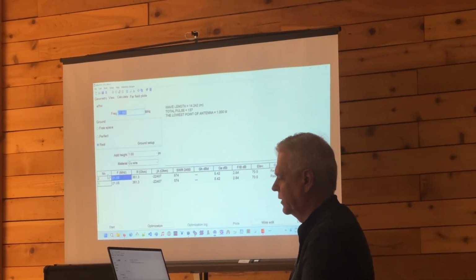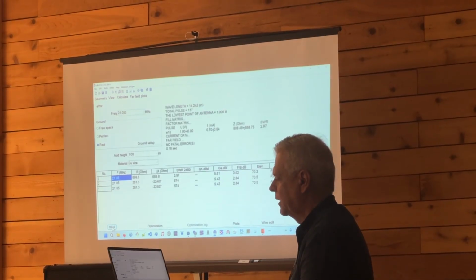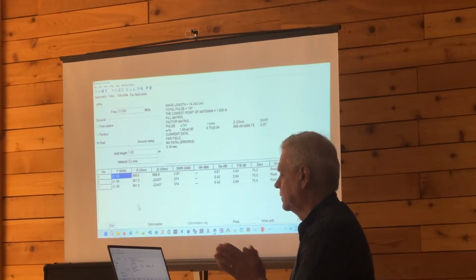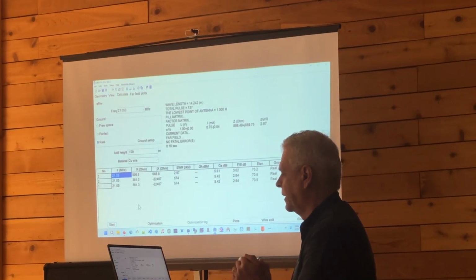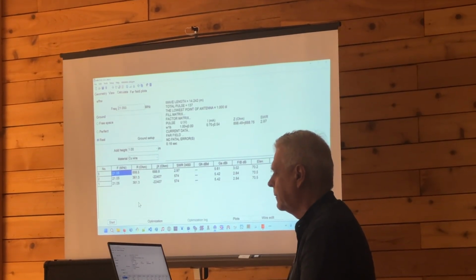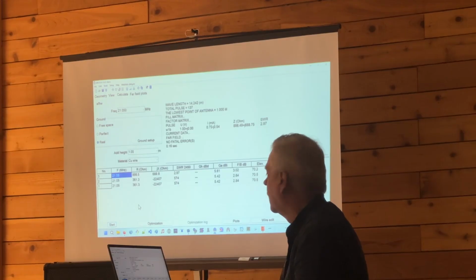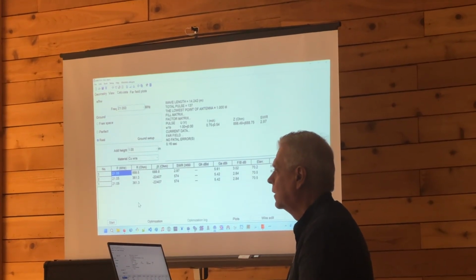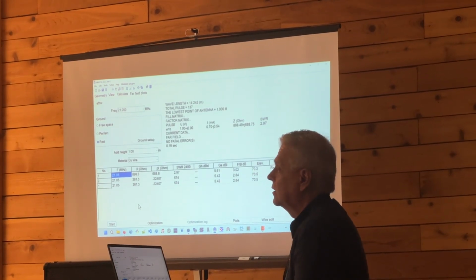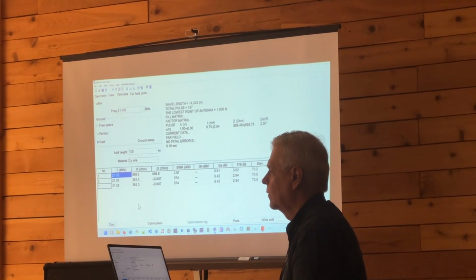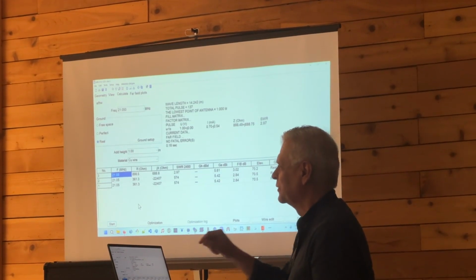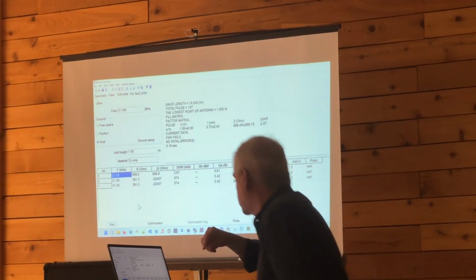Calculate, leave everything the same, click start. Okay, now this we can actually feel better about, 2.97. Still not the best, but good. Okay, go for it. I've got a question. So that counterpoise you have on there is the shield on the coax. That is. But the coax isn't gonna be 2 meters. Well, it's 6 feet. Okay, so you're just gonna have a 6-foot. Yeah. But hold on to that thought, because we're about to do something that's very useful. No, it's good, please.